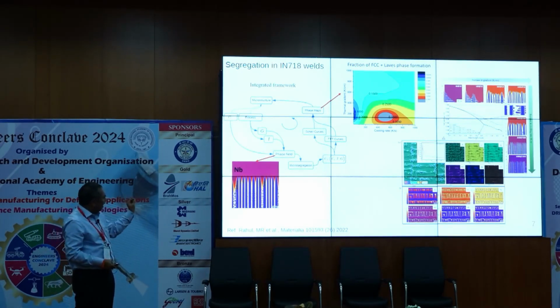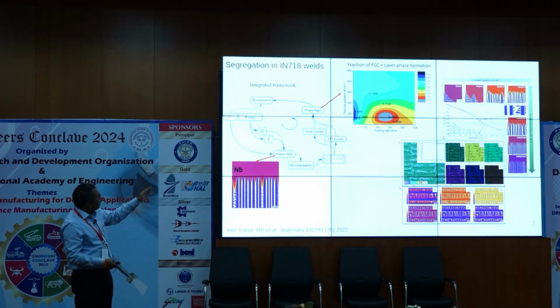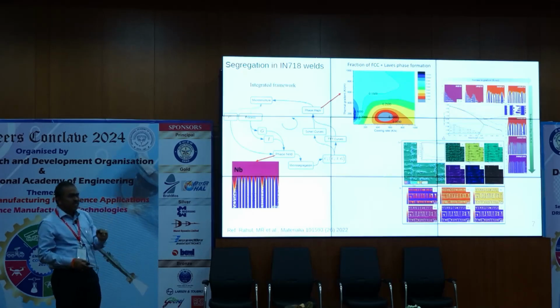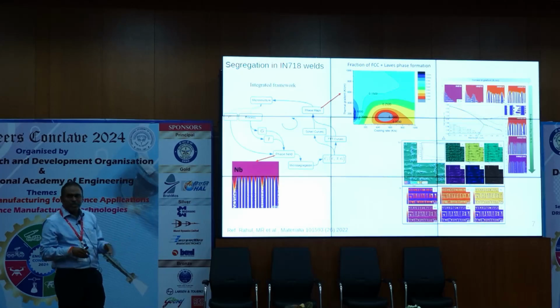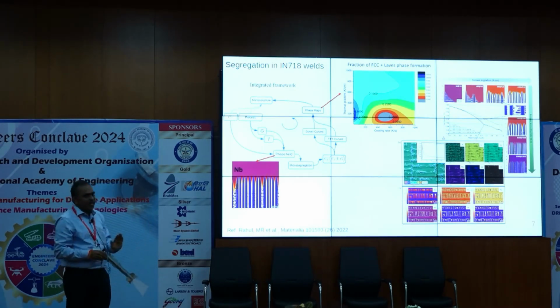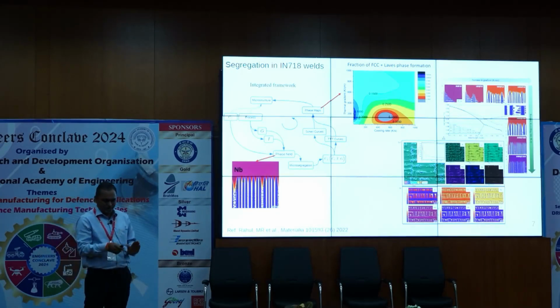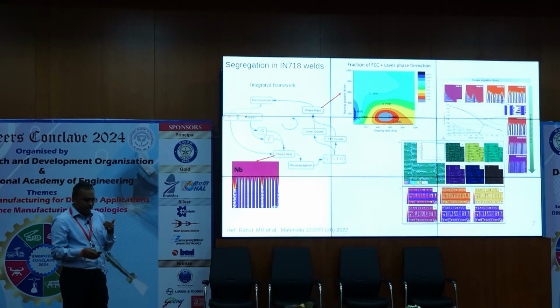And then for that segregated alloy, you can look at what are the TTT curves that are applicable to see the likelihood of a phase formation such as Laves phase. And then from there you can derive what's called the phase map. The phase map basically is in the processing parametric space of cooling rate and thermal gradient, where you could see that the gray region is bad news and on the left-hand side the blue region is good news, and therefore you can design which way you should match the process so that you can avoid the larger space during the welding process. This has been validated with the open literature, and this kind of map is now possible because of high throughput computations that are possible due to the high performance computing that is available.